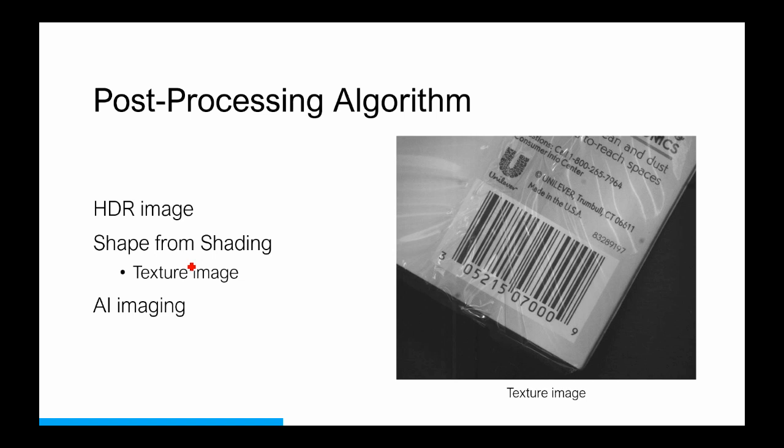The downside to them is, you're taking multiple pictures, you're combining pictures, so your processing time and the time it takes to get each picture and the result is going to be longer than just solving the problem from the lighting standpoint. And the effectiveness may or may not work on everything. So, if you want to try it, I won't say no, but there's definitely other ways that I just talked about that might get you the same results that are faster and a little easier.